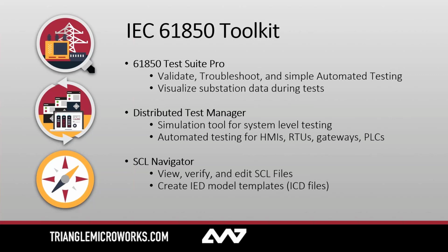For DTM, that was what was driving the simulations behind Test Suite Pro during the demonstration today. And to create that simulation, DTM can parse an SCD file and automatically create a majority of the behavior to simulate logical nodes in the substation, like the recloser that Christoph showed you. DTM can also do complex automated testing to validate things like gateway mapping, state tables, or test sequences from a spreadsheet. It can also test reaction of a system to a simulation of extreme conditions that are difficult to create in real devices.